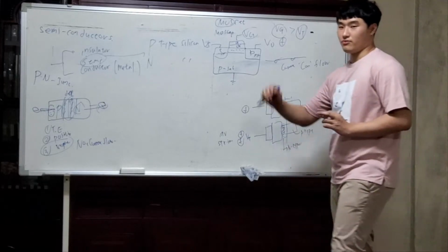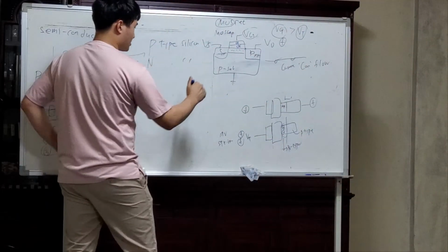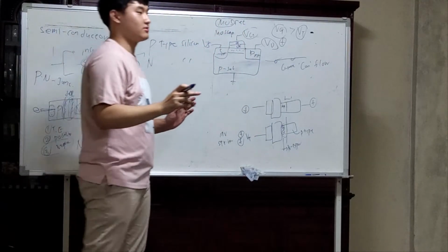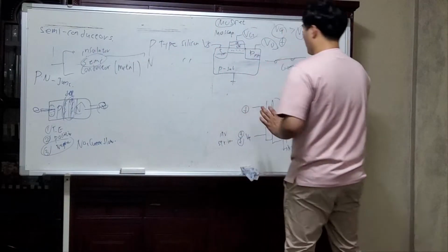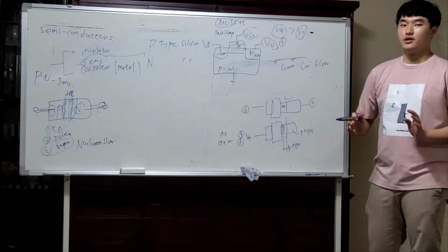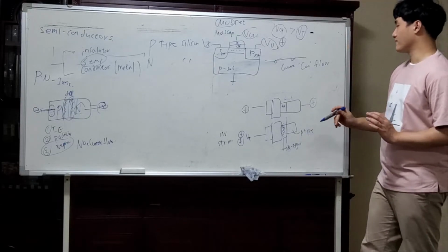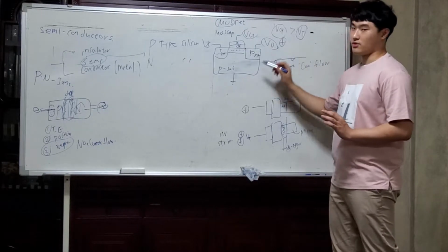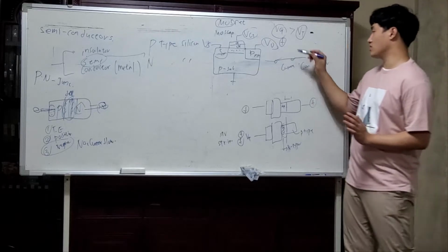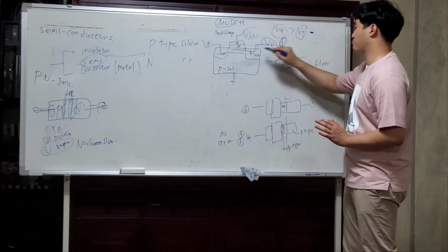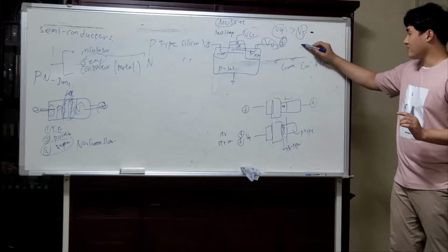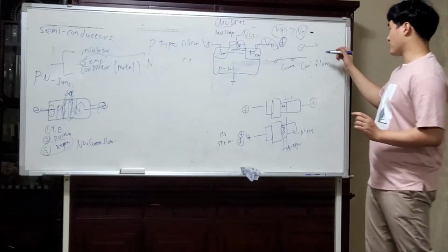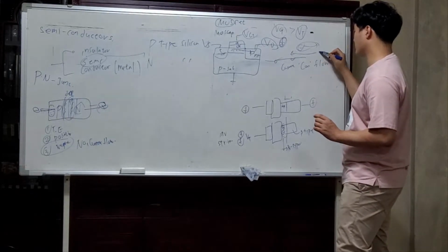So, just one more thing. If we apply the voltage at the drain, only heavy polysilicon of the N-type for the drain part, then the electrons will be attracted to the channels, electrons will be attracted to the positive bias here. But we know, if the electrons move, then the current will be induced in the opposite direction of the electron movement.